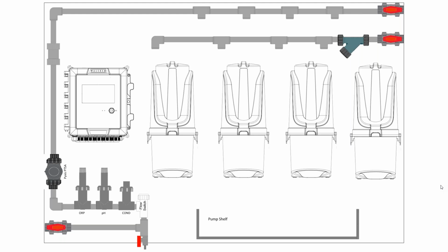It does vary on the product and application, but it's typically about a 4 to 8 to 1 comparison. So I would say a case to a case and a half of solid scale and corrosion inhibitor to roughly a drum is a good starting point, and then you optimize from there.